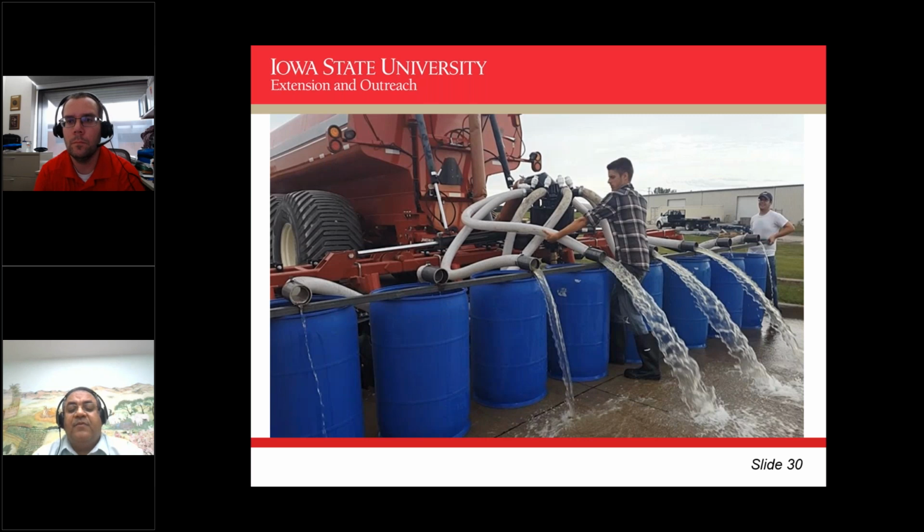So any liquid that is sitting in the hose loops itself then is a plug. If you imagine in your mind, there is no pressure in the chamber, so there is nothing pushing the liquid in the tube itself. So anything that is hanging in that loop basically does not discharge. There is nothing as a back pressure to move that fluid along.